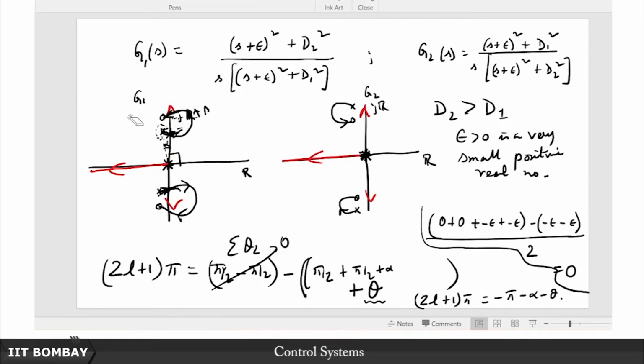All right. So that is the root locus. Let me draw this with a red line here. This is the root locus for this, and I leave it to you as an exercise to check by the same method that I have employed, that in this case when you have flipped the position of the pole and the 0, when the pole is above the 0, then no matter what value of k you choose, your closed loop poles are always going to be stable. Okay. So you see, just by applying this angle of arrival and departure, you can conclude so much about systems like these.